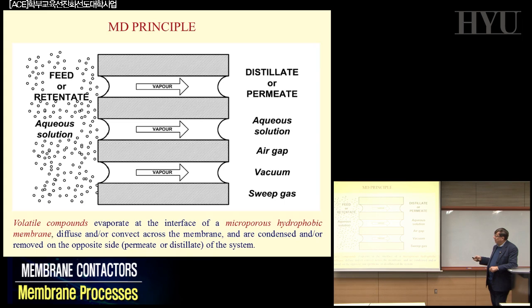You have a microporous, strongly hydrophobic membrane. We will see which material we are going to use. In principle, this characterizes the kind of structure, unrealistic. You see, all the pores seem to be equal and parallel. That's an ideal figure. Unfortunately, we don't have this, and that is the problem. In principle, this kind of configuration is not only ideal, sometimes it is necessary, because you will learn that the size of this pore is one of the parameters that we have to control for realizing membrane distillation.